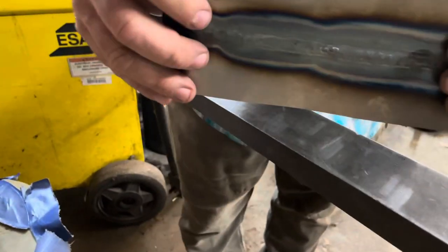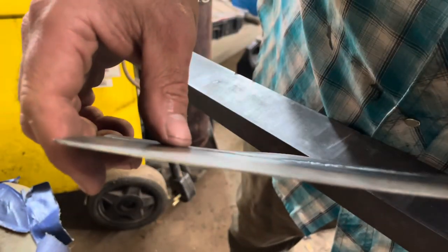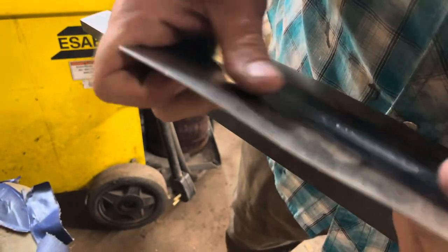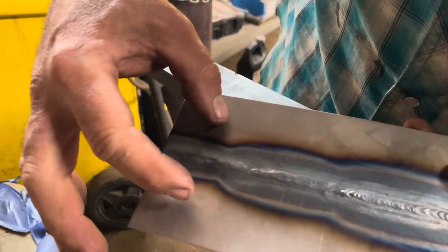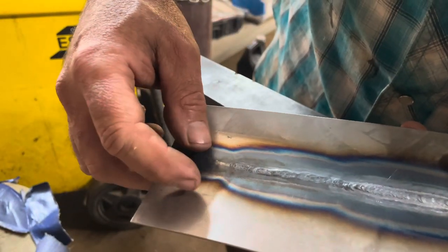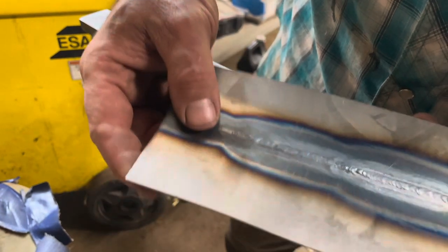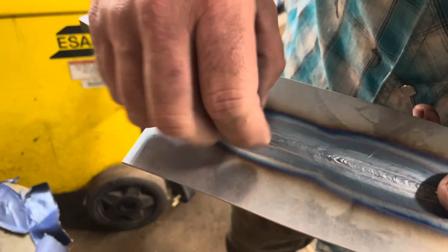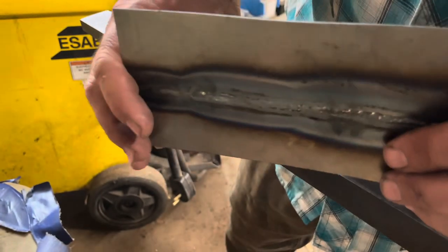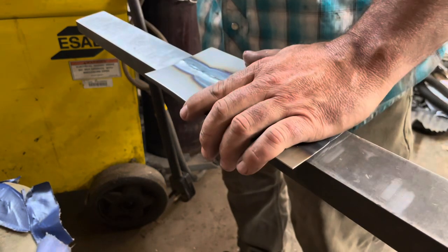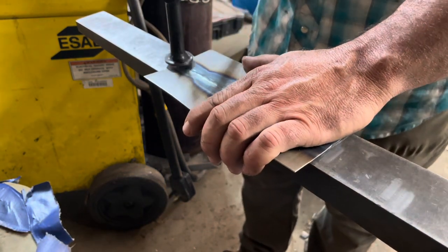So I can flex this panel back into a certain amount of flatness, but I cannot get it back to flat again. The reason for that is because as the weld puddle cooled and contracted, we were still expanding over here, but they found better, newer bonds to go to. And what happened was the newer bonds caused a bit of shrinking into the metal. So I fairly flattened it out, but you can see it's not flat. So let's go in and we're going to do a little bit of stretching on the post dolly.